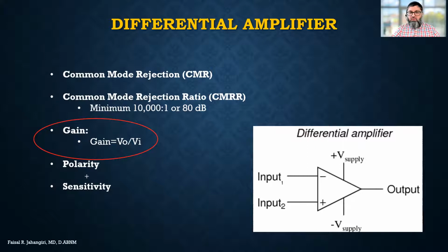So we talk about the polarity. Polarity is the direction of the signal. We need to understand the two polarities: the polarity of the signal before entering the amplifier and after. So if you say there's a negative signal, you need to be precise. The signal is negative before it enters the amplifier, or negative after it's flipped or inverted. The sensitivity, we are going to talk about it again. Sensitivity is a zoom in, zoom out phenomenon, how the signal appears on the screen.